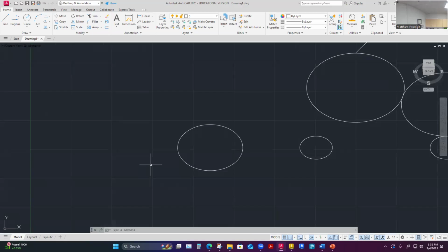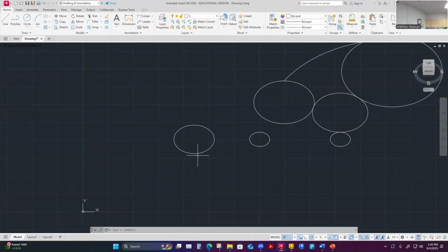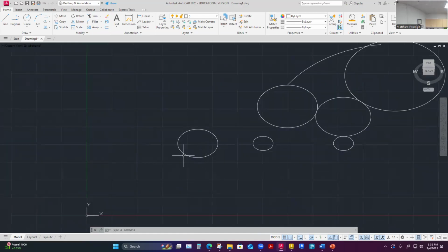It seems like a pretty simple thing to realize, but it actually has pretty powerful implications for how I represent drawings, and how features of drawings look when I change my viewing perspective. So that actually is what an ellipse is. It has a major and a minor diameter. There are two different diameters associated with this now, even though when I'm looking dead on it, it's just a circle. But when I change my perspective, I've got two different diameters to consider.